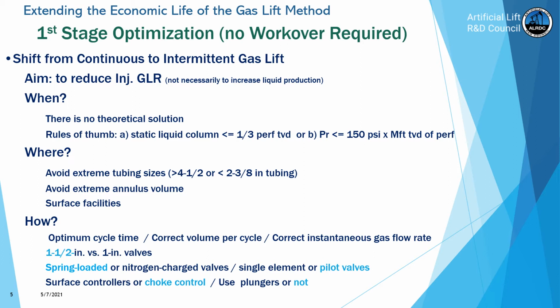Do we use spring-loaded or nitrogen-charged valve? Well, we try not to use nitrogen-charged valve because of the high flow rate that passes through the valve once the valve opens. There is a cooling effect there that makes the closing pressure of the valve be below its theoretical value.